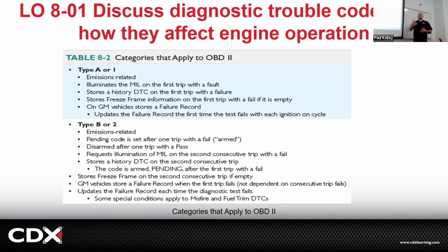So that's to help you as a technician duplicate it. Sometimes the cars only do this symptom under certain conditions. The freeze frame records the conditions, so check the freeze frame out. You might be able to get a better picture of what was happening when it failed. For example, maybe the car only has a problem when it's really cold out, or maybe only when it's really hot out. You could detect that in the freeze frame by looking at the ambient air temperature or sometimes the intake air temperature sensor. Cool. So there's a lot of information there.